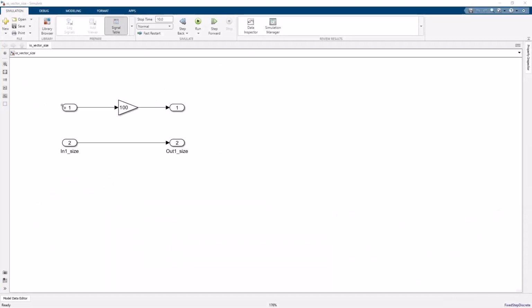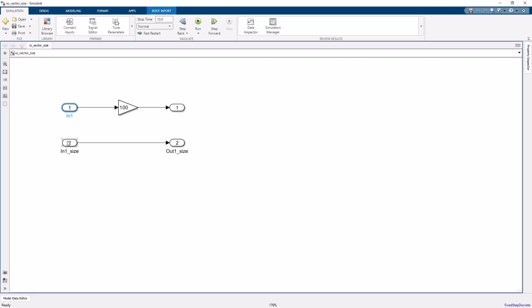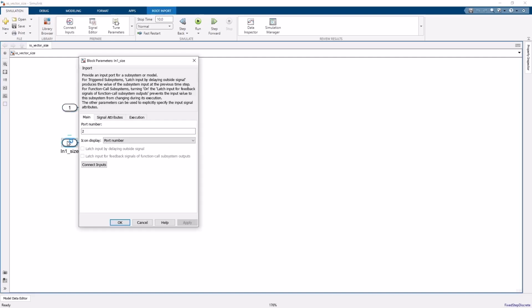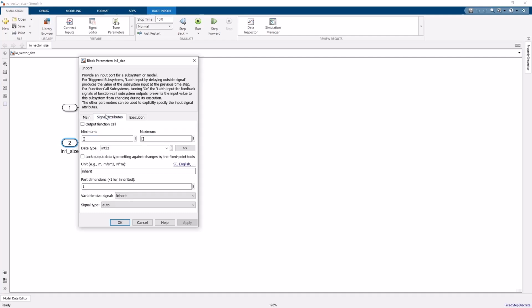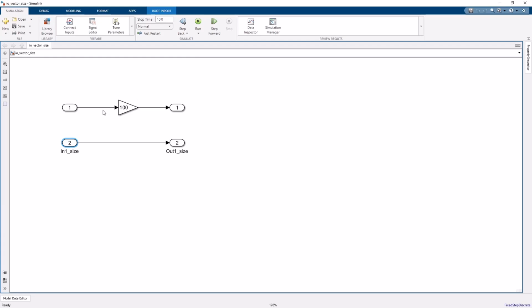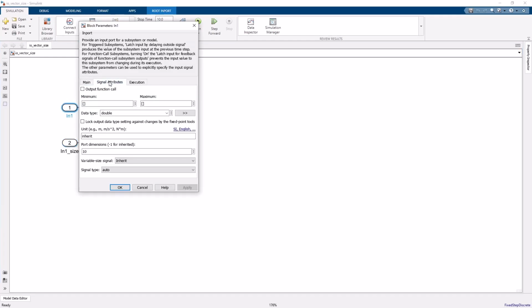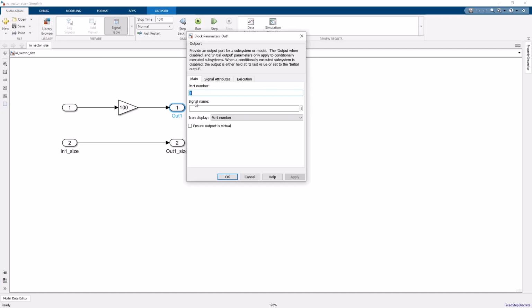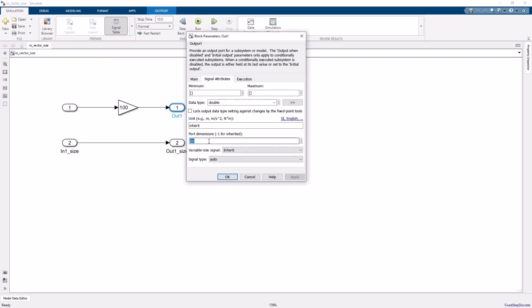Now, let's see how to handle arrays of data. Here, we have an array of doubles, processed by a gain. The RTMaps vector size value, which is variable at runtime, can be used by adding the underscore size suffix to the input or output name. The RTMaps buffer size, which is constant, corresponds to the port dimension size of the inputs and outputs. In this case, 10.